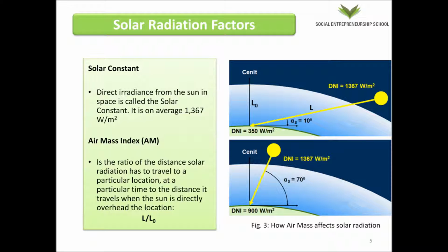You can see this on the right. During early morning or evening, sunrise or sunset, the sun has to pass through more air mass, and therefore the solar irradiance is reduced as it hits the ground. In summer, midday, as you see on the bottom, the sun has a steeper angle, and therefore more irradiance is reaching the ground and therefore your panels will produce more electricity.